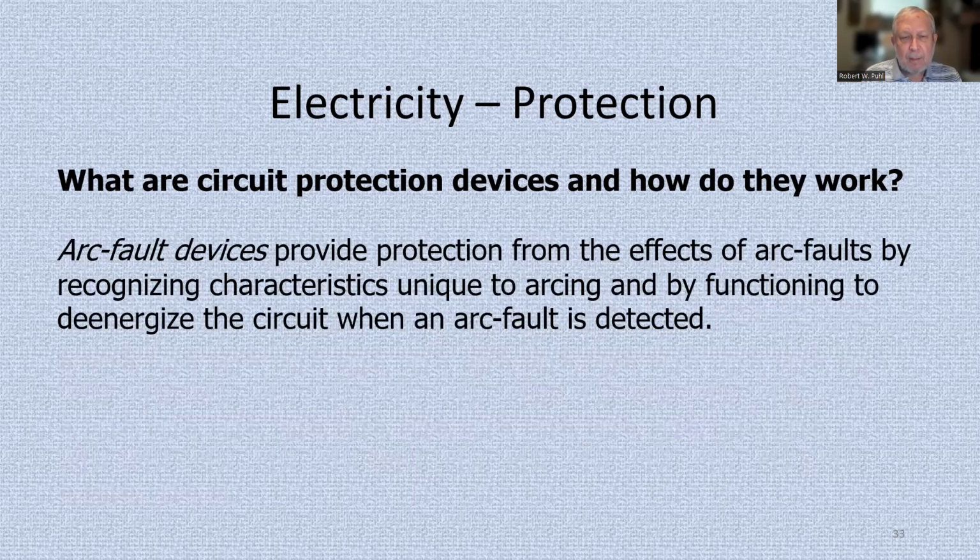Arc fault devices provide protection from the effects of arc faults by recognizing characteristics unique to arcing and by functioning to de-energize the circuit when an arc fault is detected.